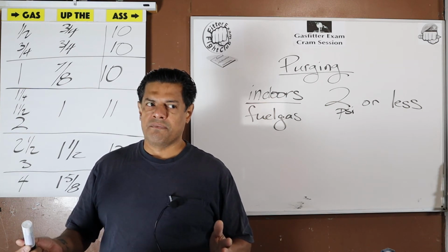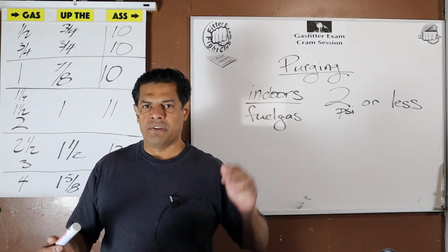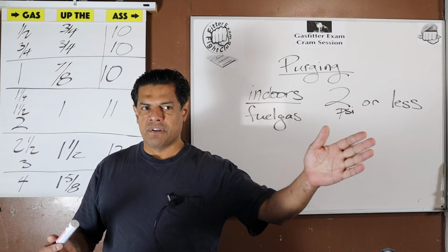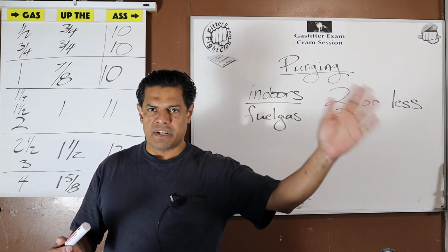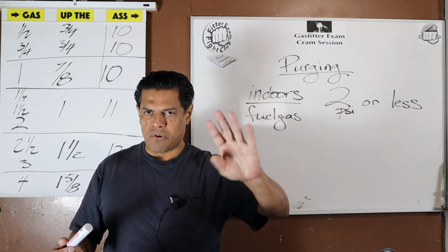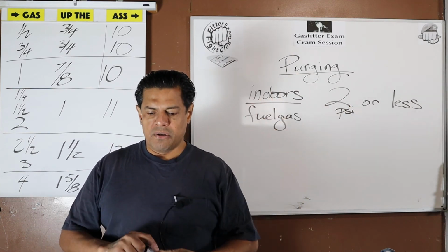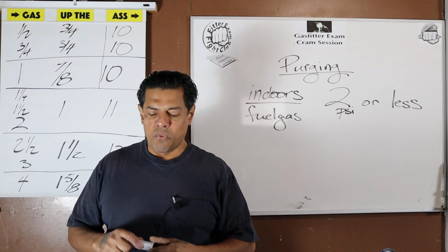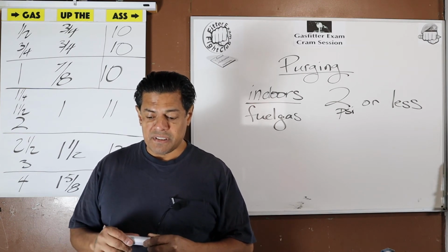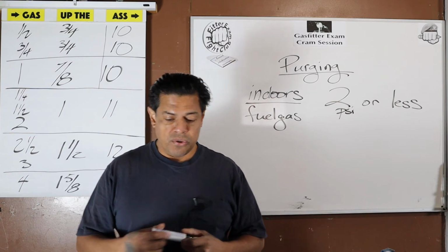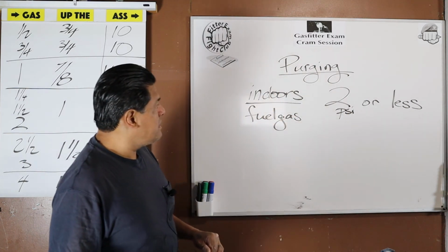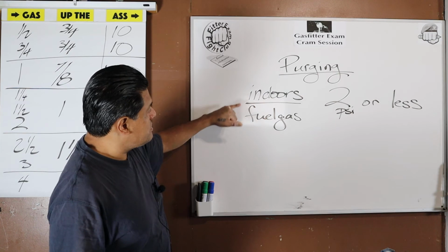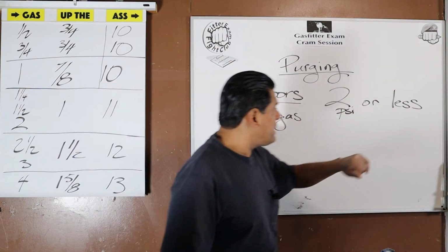Blanket statement is, if we're going to purge, whatever gases we're purging with get exhausted outdoors. Our purging port opening is outdoors. But you don't need to do that. You can purge indoors with fuel gas if the design operating pressure is 2 psi or less. Okay? You can purge indoors with fuel gas, 2 psi or less.